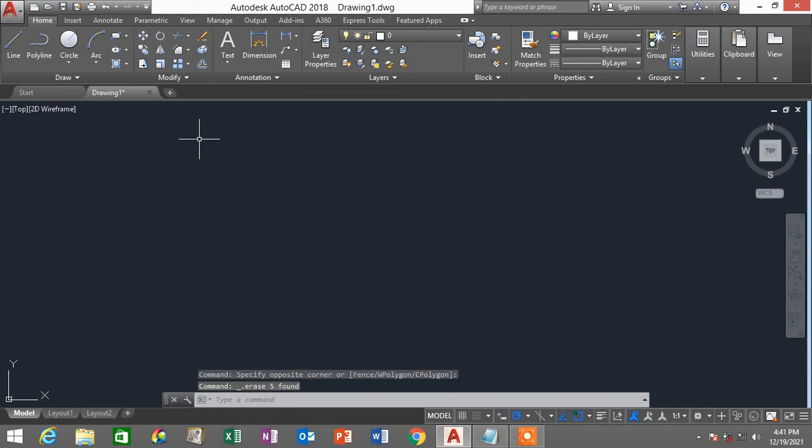So let's say we want to draw a shape, like I want to draw right now a shape of a door with a specific measurement, of course. Let's say I want to draw a rectangle that looks like a door, which has the width of 8.67 and the height of 16.87. So I just click line, I can click somewhere over here, click, polar track. So I will enter the measurement right now. I'll type 8.67 and then I press enter.